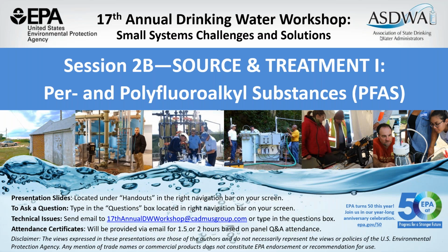Okay. Question for Scott as we wrap up. What triggered the carbon change-out? Was it PFOA at the midpoint or PFBA at breakthrough? And along with that, what do you think were the co-contaminants that were competitors for adsorption sites in the case of your project?